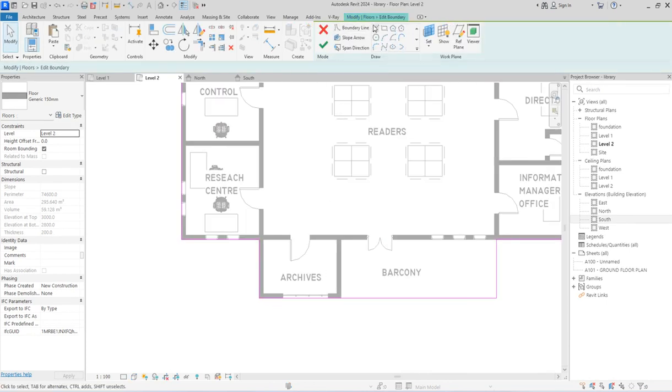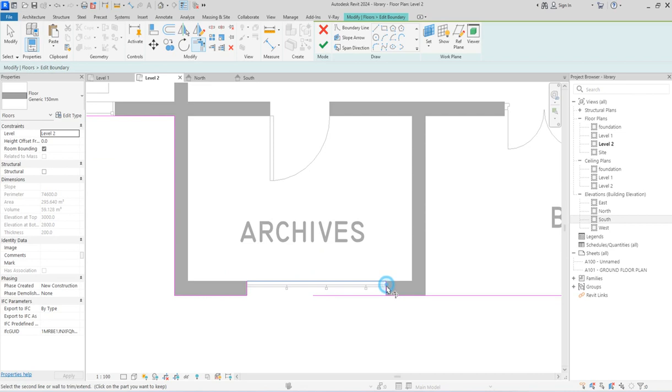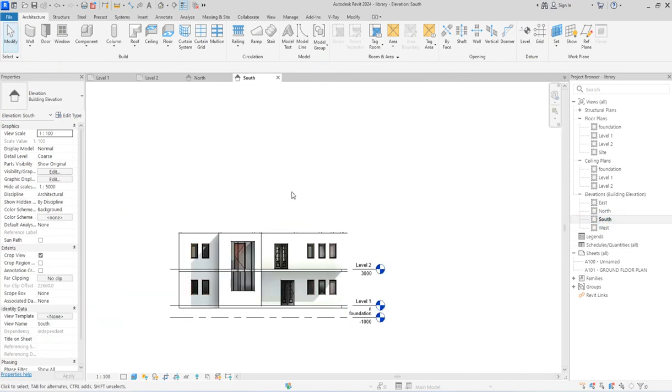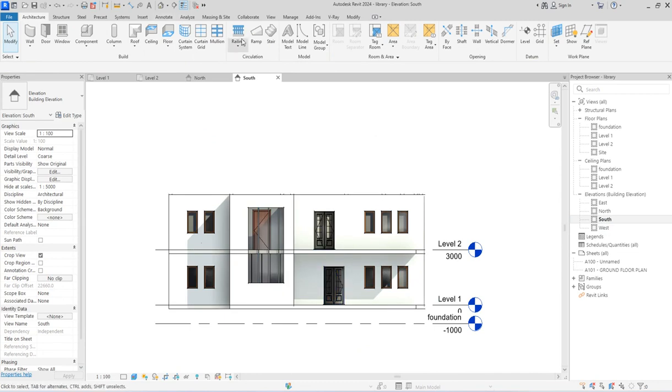At that level, then you do the same thing that you have done here. Shift. Do not let the wall cut through the windows. So split out and split this one as well. So that's what you do. You click finish, then you go back to the south elevation and see, okay, your orientation of all these things is being done. So we have it in place.